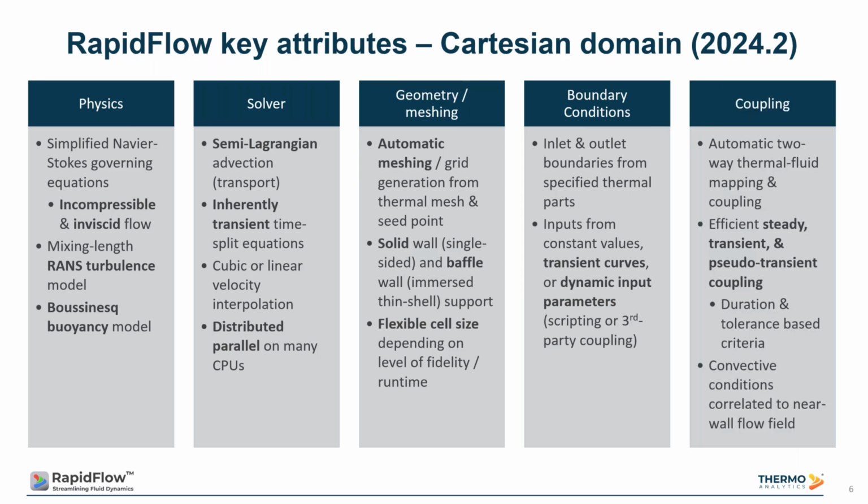And then in terms of the coupling between fluid and thermal, it's the automatic two-way mapping and coupling between the domains. We provide options to allow you to do efficient, steady, transient, or pseudo-transient coupling. And by pseudo-transient here, we mean if you have a problem where the timescale of the thermal domain is much longer or different than the fluid domain, then you don't have to march forward in time on the fluid side for the entire duration.